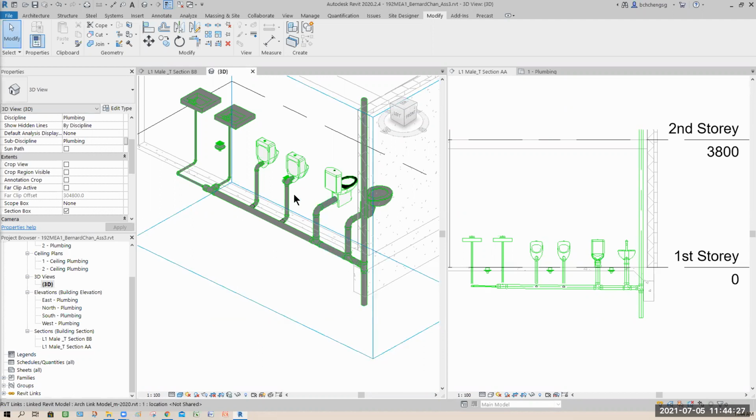That's why you can see this toilet design, they only have two. But the toilet in BCA Academy Tower, I think there are 4 to 5 cubicles, right? In BCA, only the first two connect to the main pipe. The rest will connect separately to this main pipe. You have to do that. This is a must, the practice, when you're doing sanitary work in future.